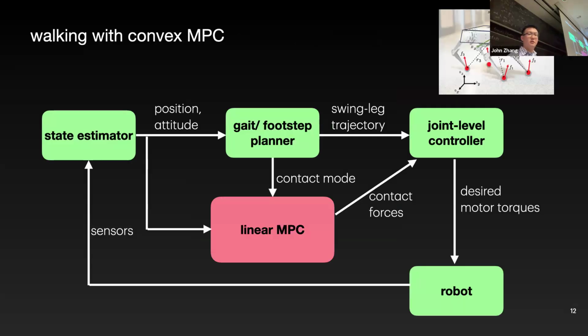Yeah, what's up? I guess it'd be negative, but at some point you basically just set limits on how much tangent force you're allowing each foot to apply. Yeah. So that's still part of the linear MPC. Typically we do a linearized friction cone, so those constraints end up being linear and you can fit them into the QP nicely. Okay. So that's where you throw in the friction cone, in the linear MPC, and that tells you how much tangential force and normal force you can produce at any given footstep. Yeah. Nice.